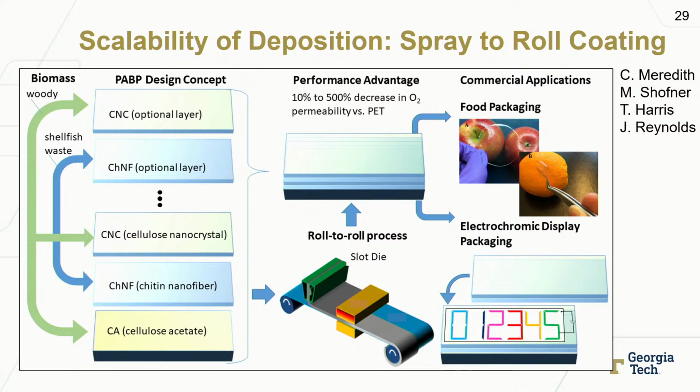But if they were like, say, a non-woven kind of mat that had porosity, once they dry with the latex binder in there, that just doesn't happen because the pores are filled at that point. So it's possible that there's some kind of wicking action that happens as they're drying, and you have these softened latex polymers, they might get drawn into this little cellulose bundle, and they may get wicked in, and maybe that's how they form films through some type of capillary action. That could be true, actually. I hadn't thought of that, but that's an interesting idea.